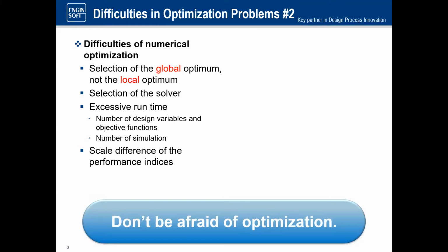But the other thing you want to do with the model is check that as design parameters are changed, the model behavior is changing in a fairly smooth way. And since many multi-body dynamics models are nonlinear, sometimes small changes can have too big of an effect.